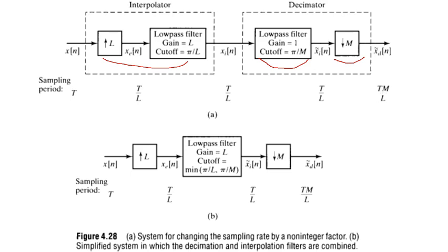In upsampling, we first upsample the signal, then we use a filter, as you have seen in the previous diagram. So this is x of n. Upsampling, this signal gets expanded, we pass it through the filter, and we have the interpolated signal. The sampling time here is T by L. Then whatever the interpolated signal is, we pass it through the filter. The sampling time remains the same.